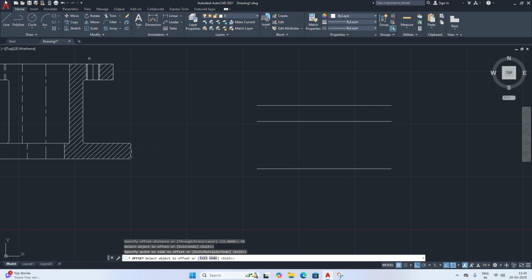Okay, now we'll draw a center line. Line mid and mid of, just type mid, you can get the center point. Enter. Now this line will offset through 12 mm on either sides. Now again we'll offset that through 21 mm. Now we will offset that through 42 mm.